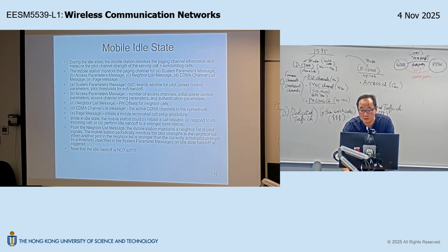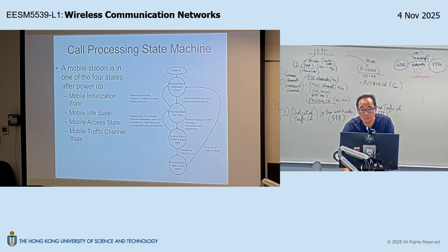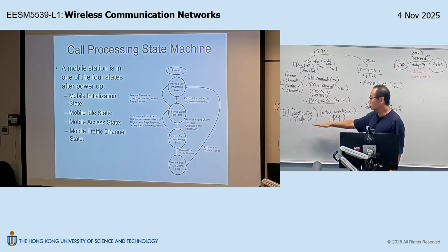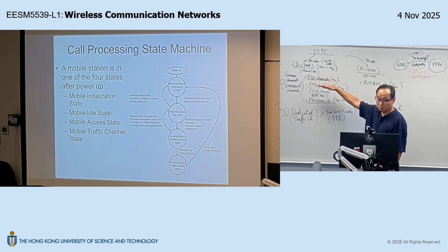Is that okay? So that will be the initialization state. Any questions? So after you finish the initialization state, you will have the ability to despread any of this downlink channel, including the traffic channel, because you know the despreading timing. Okay? And because of that, you will have to, from time to time, listen to the same channel and also paging channel.